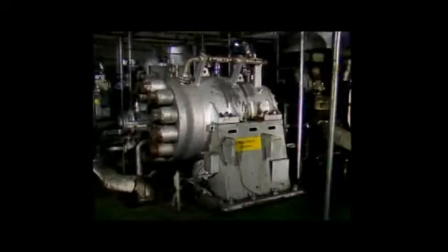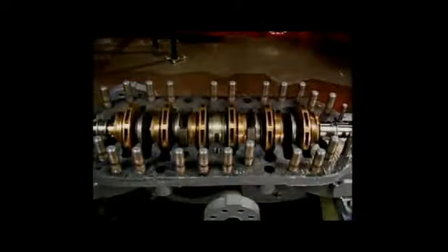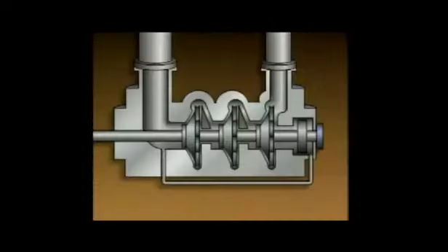In applications where large increases in pressure are needed, a multi-stage centrifugal pump is often used. A multi-stage centrifugal pump contains two or more impellers in a single casing. Here's a simplified illustration of a multi-stage centrifugal pump. Since it has three impellers, it is a three-stage pump.